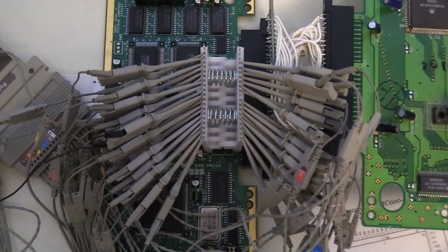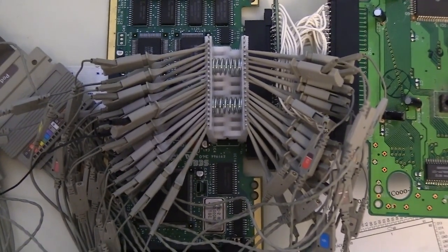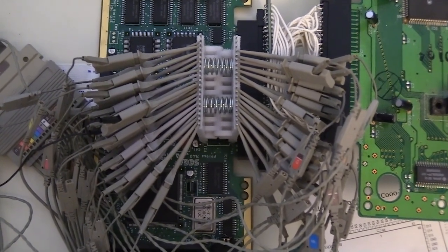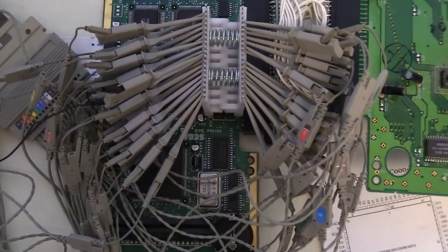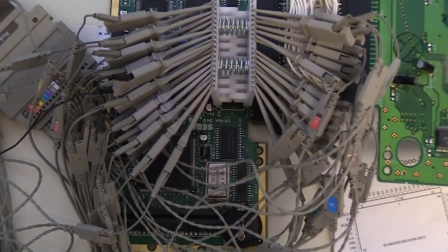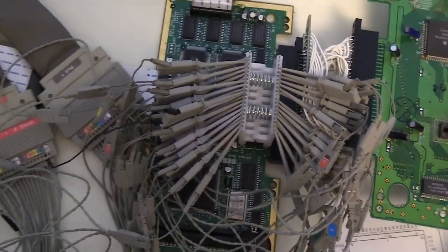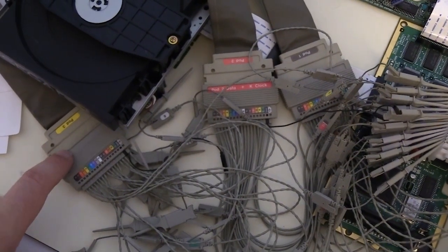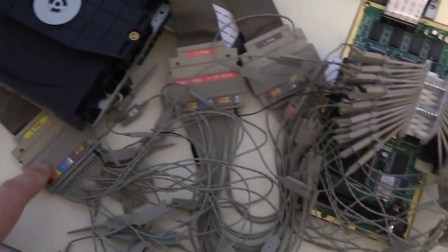So basically the way it works is, the CPU sets an address on the address lines, then when chip enable and output enable are both held high, that's when the data for that set address is read out from the EPROM on the data lines. So the 2 control circuits for the chip enable and the output enable are here for pod 3.